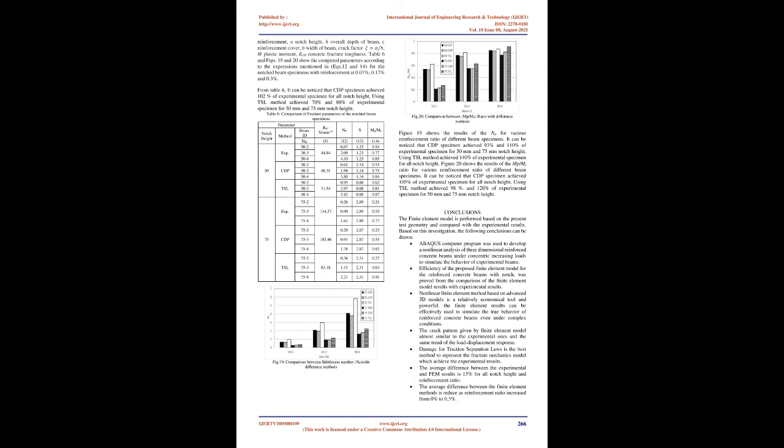According to the analytical formulation of the bridged crack model, the overall behavior is a function of the reinforcement brittleness number NP, defined on the geometrical and mechanical parameters. A brittleness number, NP, represents a ductility parameter, Eq. 12. Therefore, a brittle response with a softening branch after the peak cracking load is expected for low values of NP. By increasing its value, it ranges from 0.1 to 15 as ductile response is predicted, with a hardening behavior after the cracking load and a large inelastic displacement due to steel yielding.